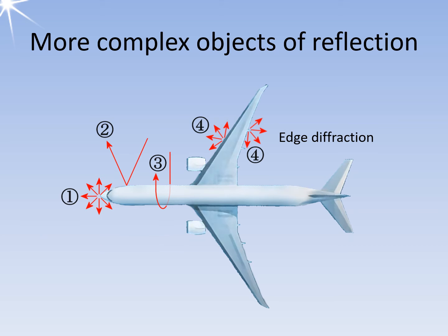Fourth, edge diffraction. Like scattering from tips, the scattering from edges is less significant. They become progressively less important as the radar frequency rises. This also applies to the corner diffraction, of which only 1 of 5 is marked here.